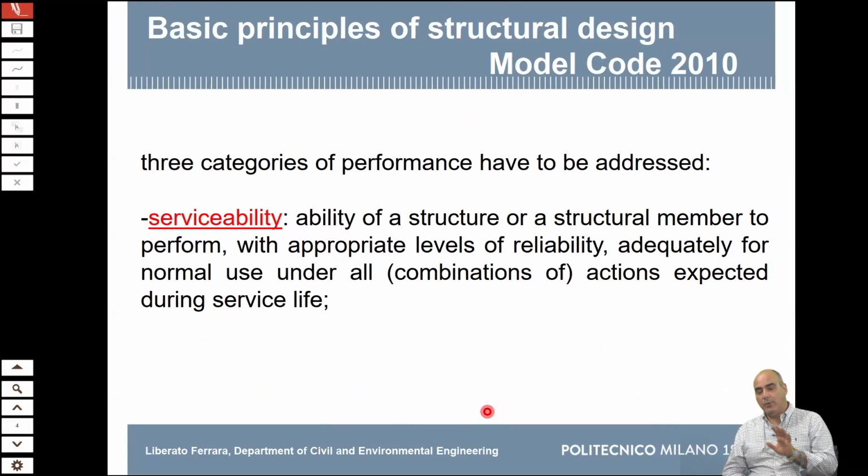Okay, so basically, what are the requisites for which we design our structures? We first of all have to address serviceability. It means that we have to guarantee that under all the possible combinations of actions that we expect during the service life, remember that combination does not simply mean a sum. Combination is something which brings also space and time concepts into place. But under all the combinations of actions, you shall guarantee that the structure remains fit for the use.